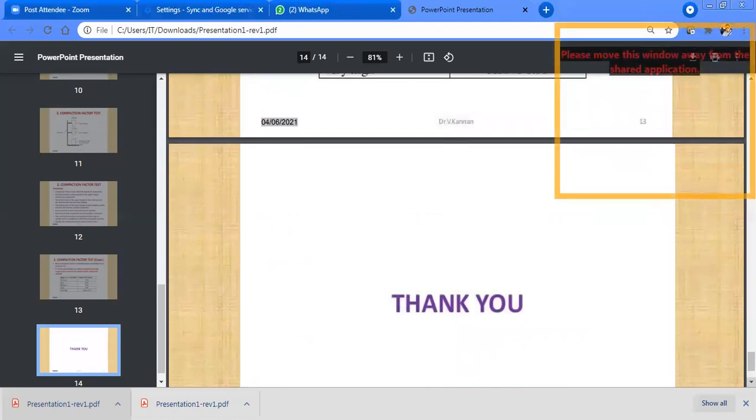I will let you know some important things which you need to keep in mind at site when you are going to site as a civil site engineer. When you are a civil site engineer, you are dealing with concrete at site. What are the main factors we need to take into consideration? First of all, when concrete reaches site, we have to check the class of the concrete. The second thing, we have to check how much quantity of concrete will be poured.